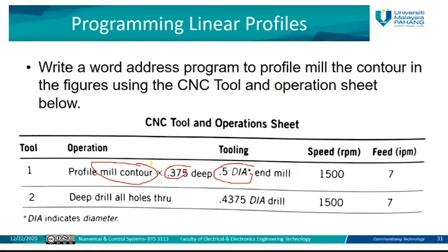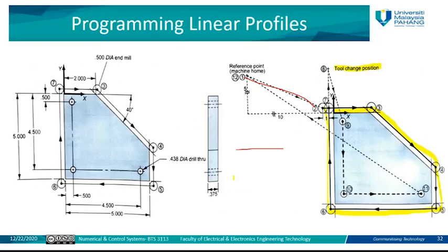If you say T2, it gives you tool number 2. Usually there are some embedded tools inside the machines, with their sequence numbers. So during the programming, you just need to select the correct tools which you require for your operation based on the given information here.